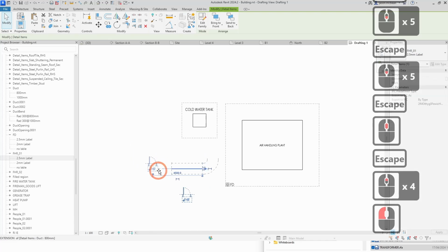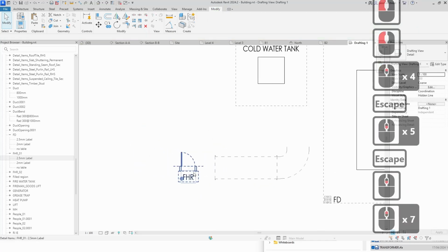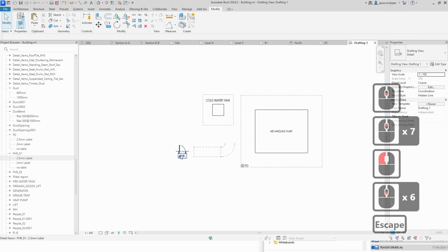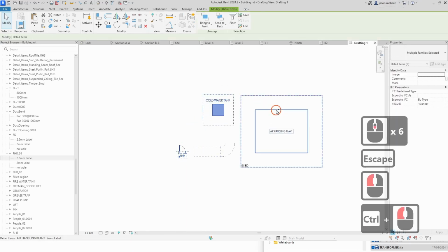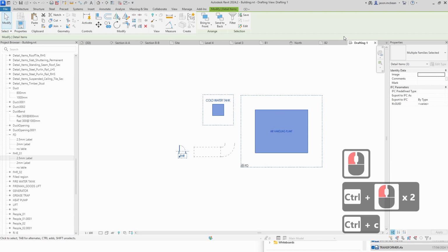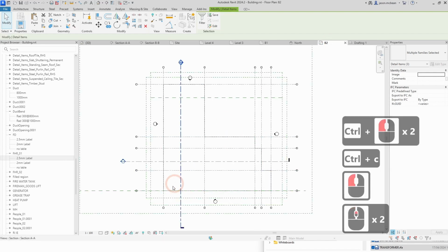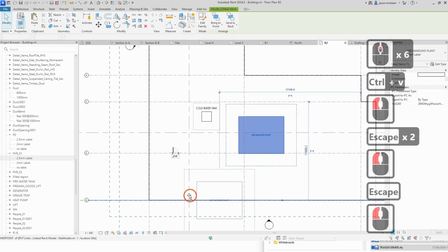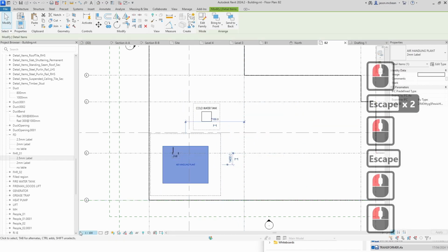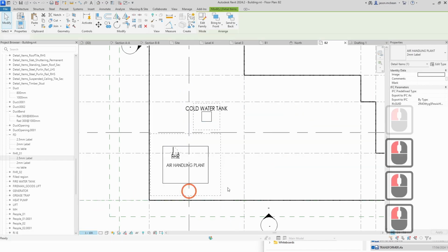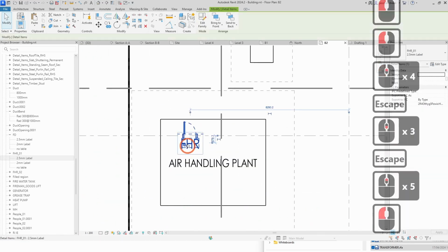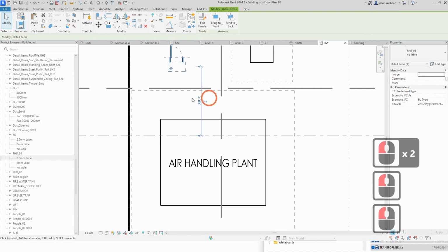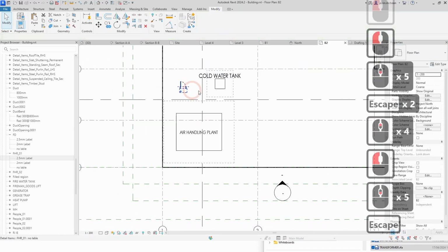You can test things out. So drafting view is quite handy to see how things work, test them. Then when you need to use them in your basement, for example, you can grab all this information just like this. Control C, go to your basement view, basement 1 or 2. Now you can start pasting this information in here and then using this information in the view correctly. Remember, these are going to be at a certain scale. You're going to draft a lot of information in the beginning, and remember, if you don't want to see the labels, you can simply switch off the labels. Okay, then you can draft around this.